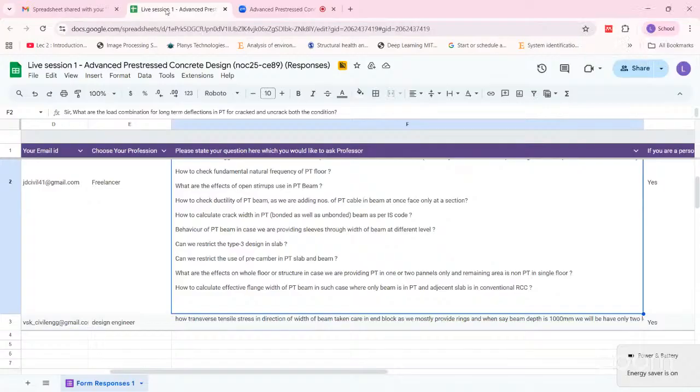Also, the pre-camber achieved on site, on a general site of a commercial or residential building, is not in the hands of the engineer, but is mainly taken care of by the contractor. And if we are providing 50 camber and they are casting the top at the same level, then our section is reduced by 50 at the most critical section.